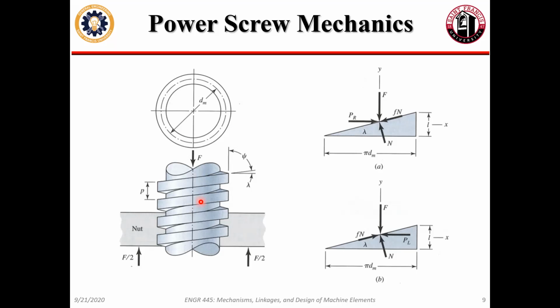You could also use a thrust bearing or something like that. You have to eat up that thrust load somewhere. It's not only pushing on the thing going to move, it's also pushing on the quote unquote fixed object as well.